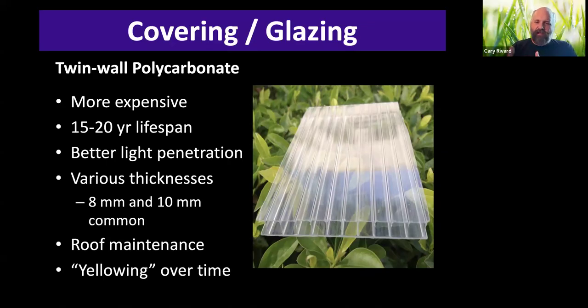You can get it in a couple different thicknesses. I often tell people for a high tunnel, use the 8 millimeter. For a heated greenhouse, use the 10 millimeter. But you don't have to follow that rule necessarily. The 10 millimeter will give you a little bit more insulation.